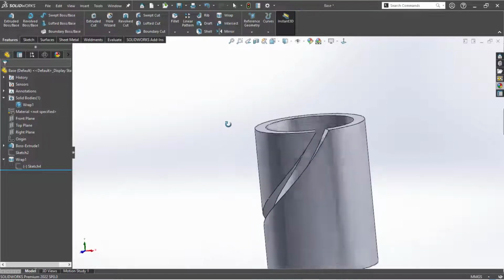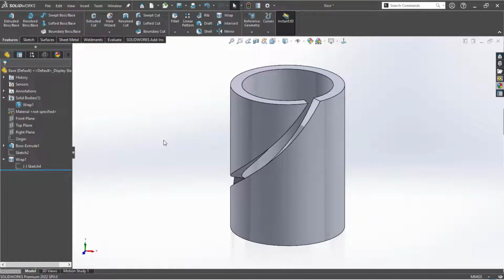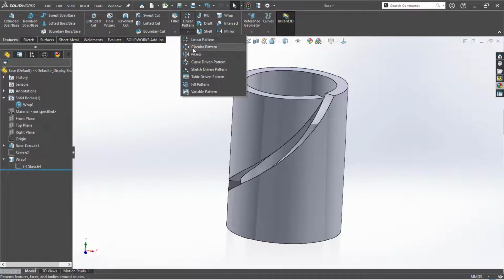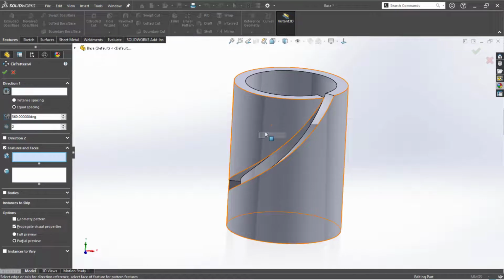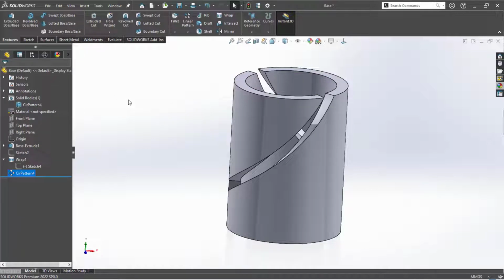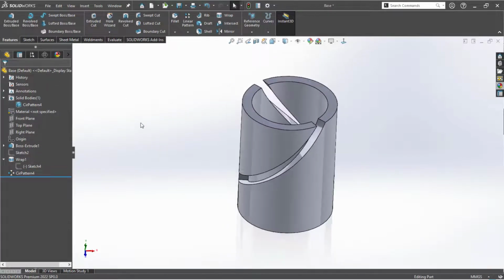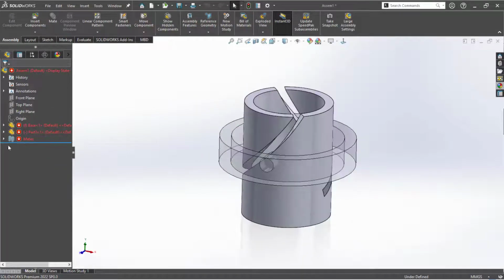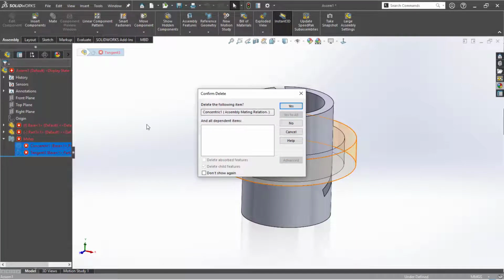At the bottom it is 3 mm. So now I'll do the same thing. I can use the circular pattern and simply use the feature mirror. This is fine. You can save it, and you need to eliminate these mates because we have completely recreated the model, right?